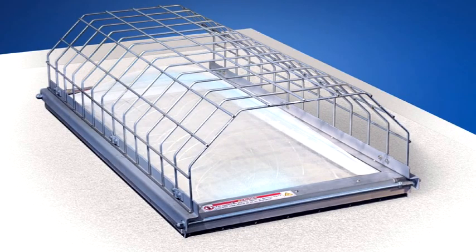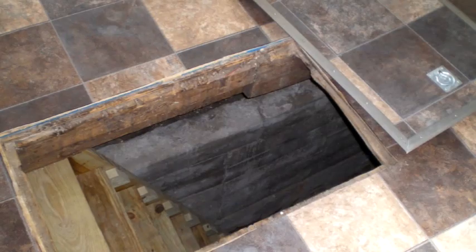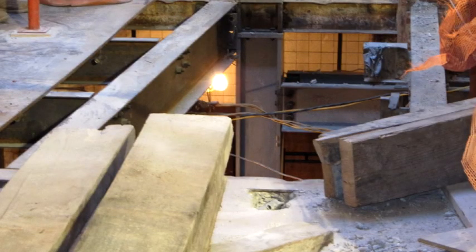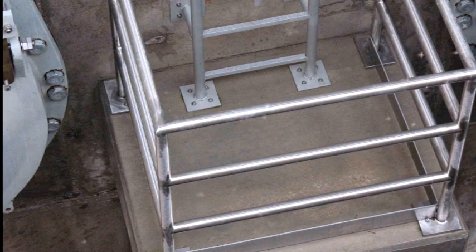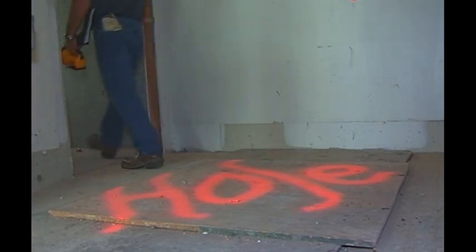Floor openings include skylights, stairways, ladderways, hatchways, pit and trap doors, manholes, and temporary floor openings. Every floor hole should also be guarded by either a standard railing with toe board or a cover of sufficient strength and construction.